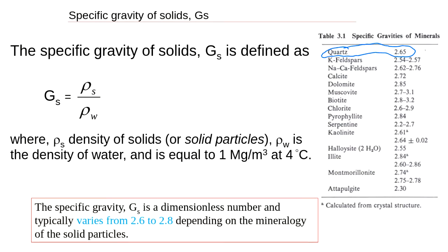Quartz is very resistant to the weathering process, so if we have it in rocks, we also have it in soil. But other minerals, the ones that make rocks hard and heavy, will be changed to what we call clay-like minerals like kaolinite, illite, montmorillonite, halloysite, because of this natural process.